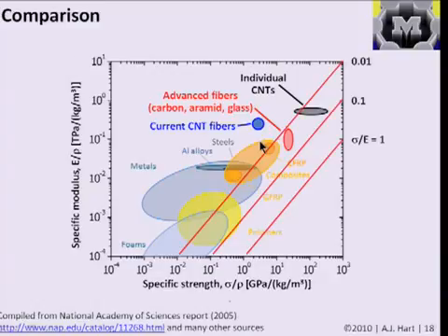And so if we look at this chart and plot lines of constant values of sigma divided by modulus, here strength divided by modulus, you can see that our theoretical limit of 0.1 is not approached within an order of magnitude by many of these materials. In fact, with measurements of individual nanostructures, individual nanotubes, there's a lot of variation in those measurements, and we'll see the origin of that later, but there we can almost get to this theoretical limit, where some researchers have measured carbon nanotubes that fail at a tensile stress of 100 GPa, or 0.1 TPa, terapascals, which is 1/10 of the axial modulus of graphite.